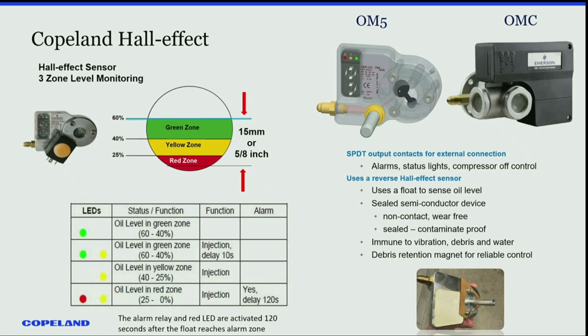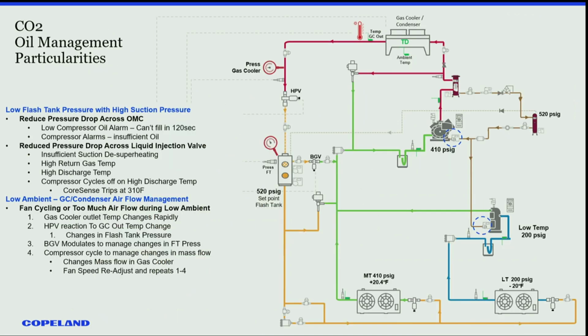So that's important. They measure based on a Hall's effect sensor, and the actual magnetic portion is in the inside wall of the device, and the float has a sensor on the circular part. So as it's measuring, the sensors are measuring its position, and that's how it does it in there. So making sure that the control is level is also important. Don't stick that on the compressor crooked. So that's important.